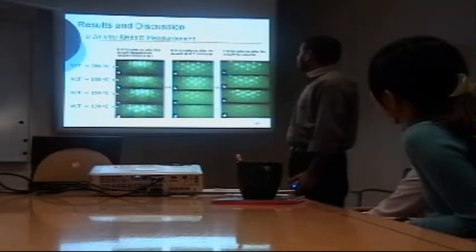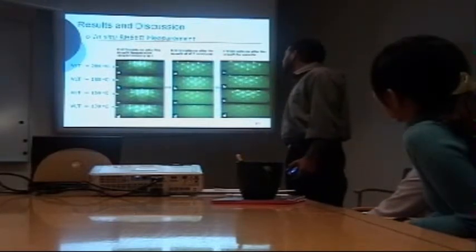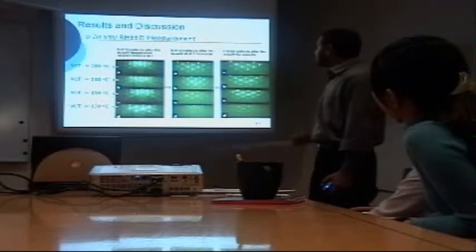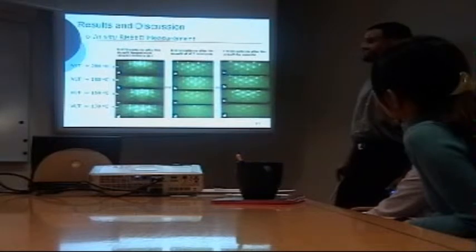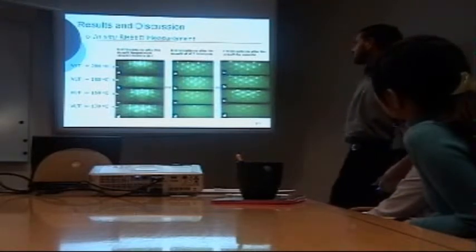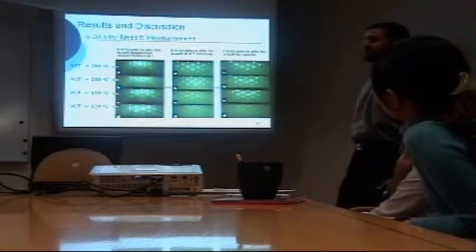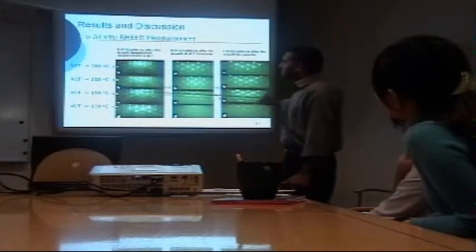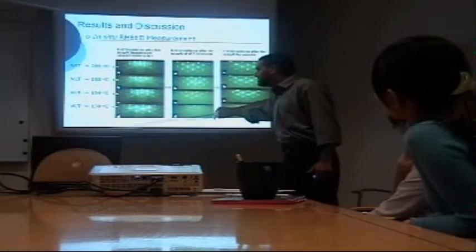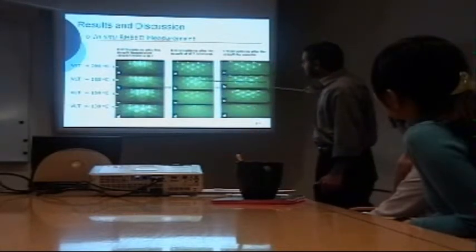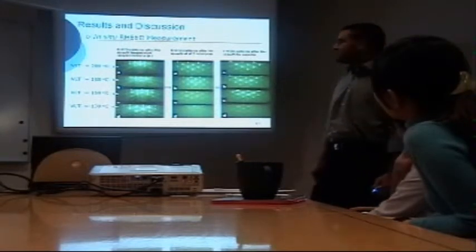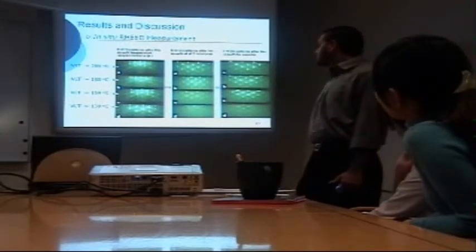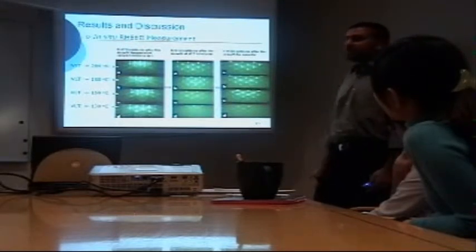After the growth of the very low temperature silicon germanium layer, we can see a clear bulk pattern indicating that the surface is dominated by 3D roughness. And we have also seen that in the very low temperature growth step, when we decrease the temperature from 200 degrees centigrade to 130 degrees centigrade, the intensity of these spots decreases, indicating that the periodicity of the single crystal starts to degrade and it tends to become polycrystalline.